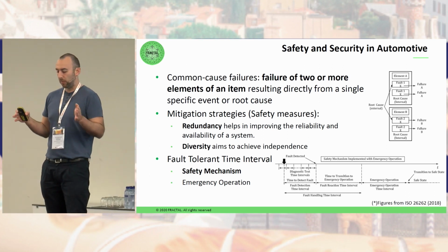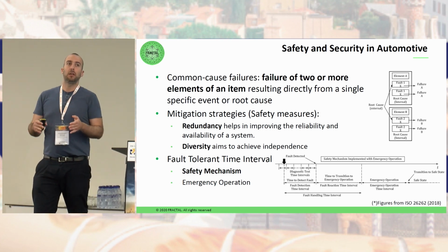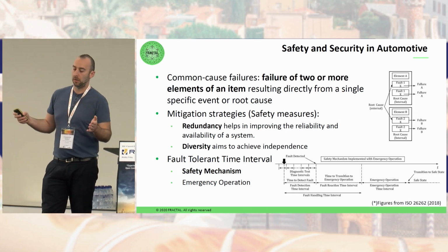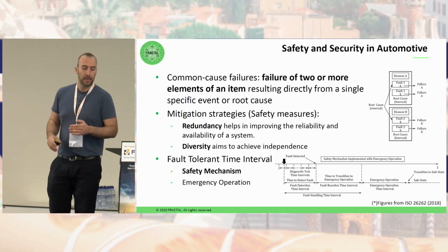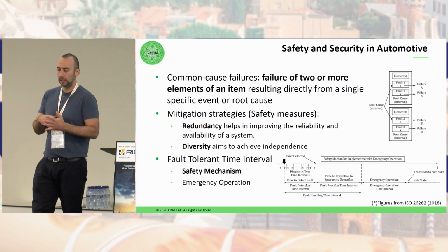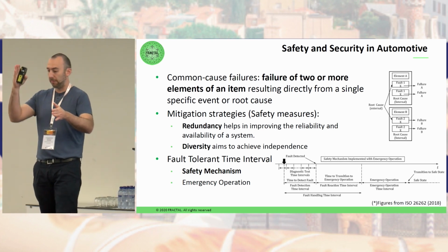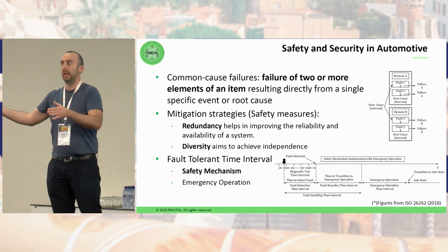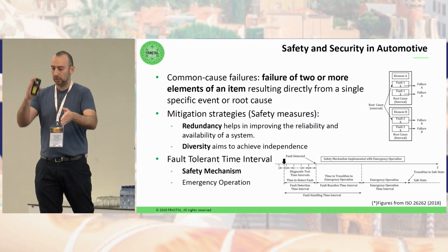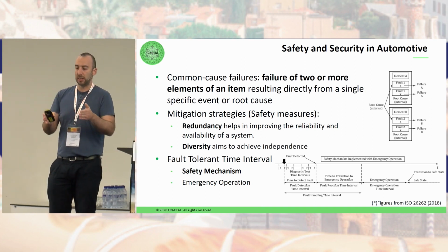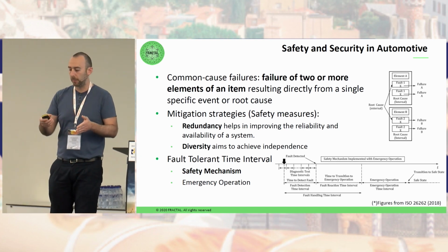Then there is the part of monitoring, which is also relevant, because in safety, during the concept phase, once we know that the functionality is safety critical, you need to calculate the time between a fault occurring, a failure happening, and then an accident. You want to address this when a fault occurs so that it does not lead to a failure. This is the strategic time when you want to put safety mechanisms in place to avoid that.